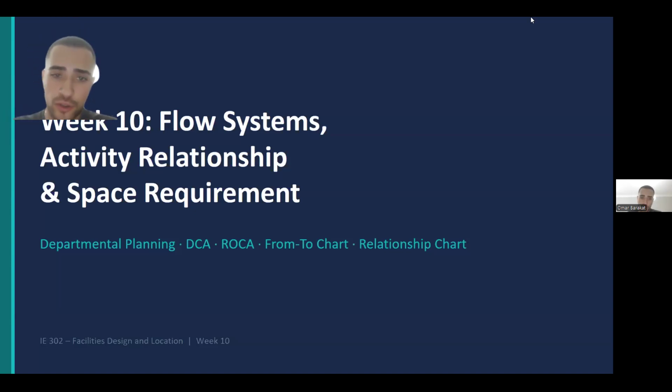In a traditional job shop, a part might travel back and forth across the facility 5 or 6 times before it's finished. Each trip adds time, handling costs, and risk of damage. In a cellular manufacturing layout, the same part stays in one cell from start to finish. The difference isn't just aesthetic, it's measurable in lead time, inventory, and cost.